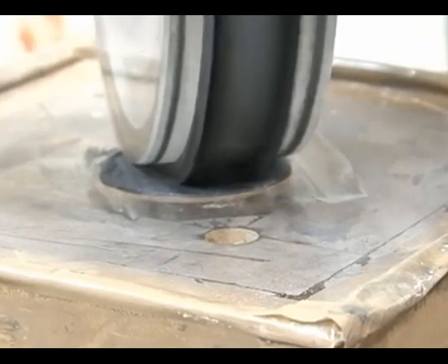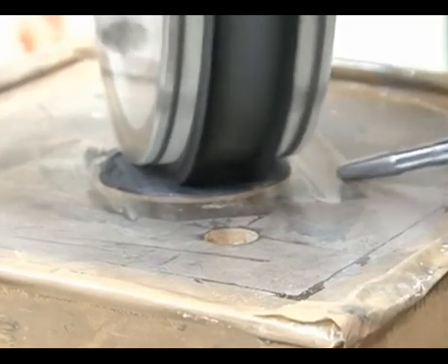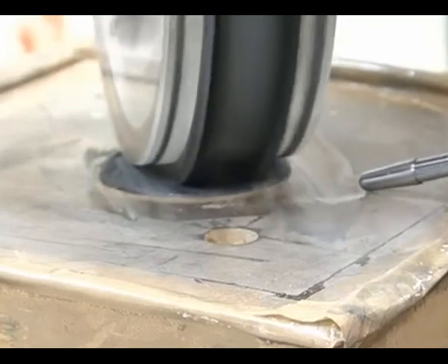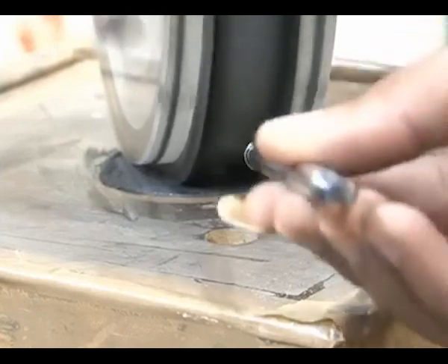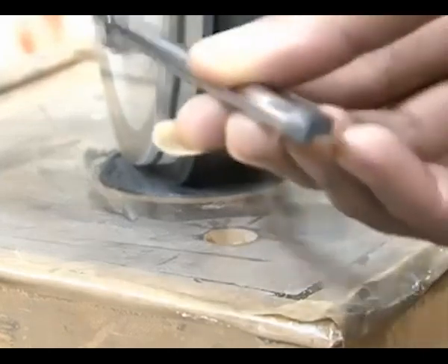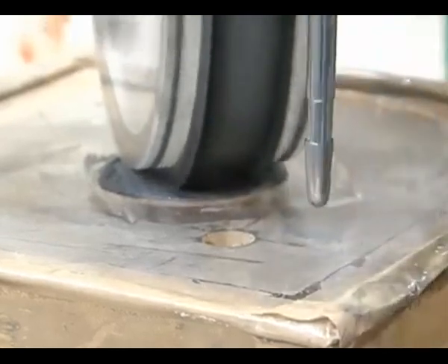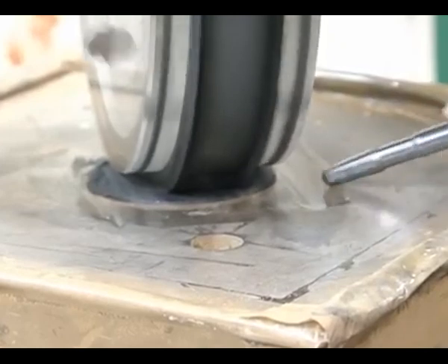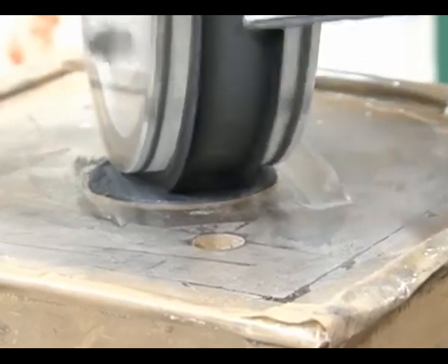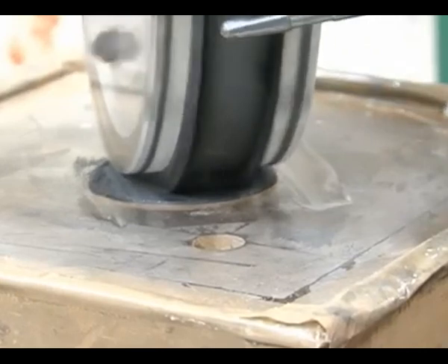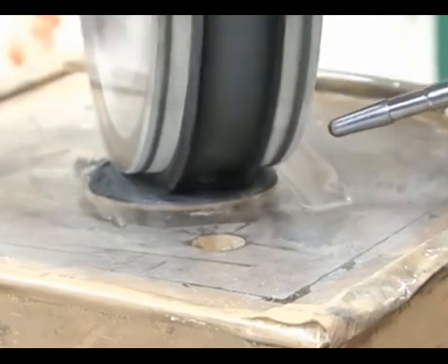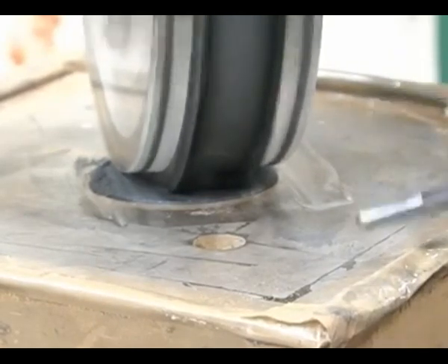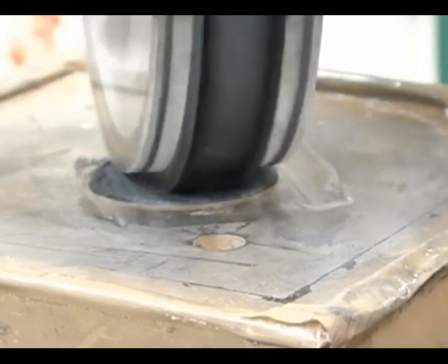Here you can see the stiffened MR fluid is interacting with the workpiece surface. At the finishing zone here, two types of forces are exerted on the workpiece surface. One is tangential force in this direction. It is applied by the rotation of the carrier wheel, and another one is the normal force in this direction. It is due to flow of stiffened MR fluid through the converging gap, because the gap is a little bit smaller than the thickness of the ribbon which is applied on the wheel, and the hydrodynamic action of the MR fluid also creates some normal force. This process is continued till the desired surface finish is achieved.